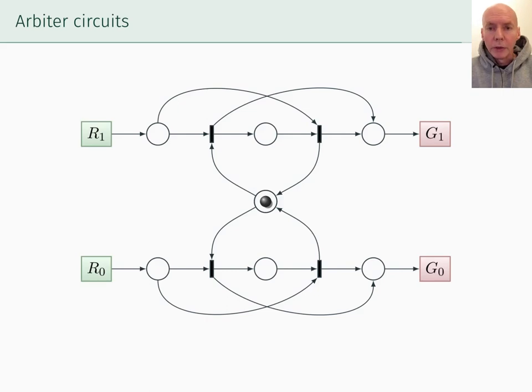Like I said, you can't make an arbiter out of logic gates. You probably won't find one on an FPGA. You'll be lucky to find one in any standard component library. You'll probably just have to get some silicon guru to do a custom transistor layout. But the good news is, you'll only have to do that once. Once you have an arbiter with two inputs, you can use that to build arbiters with any number of inputs.